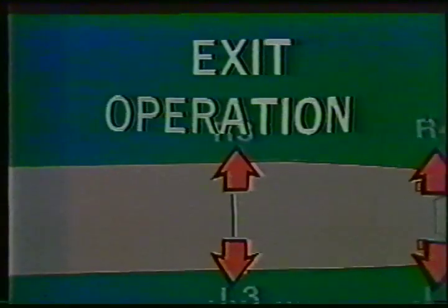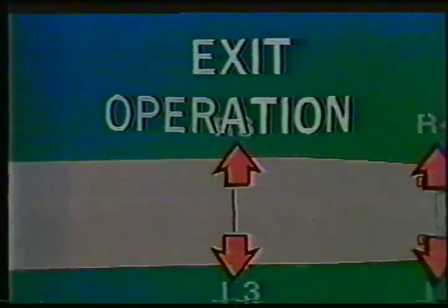There are 8 door exits on the A300. 2 of these, L3 and R3, are smaller emergency doors. The rest are large passenger loading doors with dual-lane slide rafts. Despite the size of these doors, they are remarkably easy to operate.